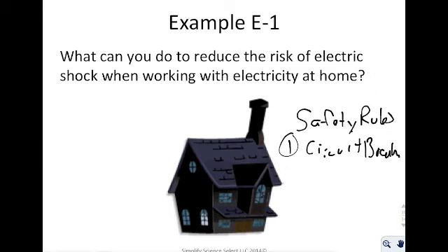So if you're ever replacing outlets or switches, go to the garage or wherever your circuit breaker is and flip off the electricity to that room or the house, depending on what you want to do, and then start to work. Okay, make sure you wipe away all your sweat, put one hand in your pocket, wear gloves, specifically highly insulating rubber vulcanized gloves is really what you're looking for, not just, hey, my hands look pretty, gloves.